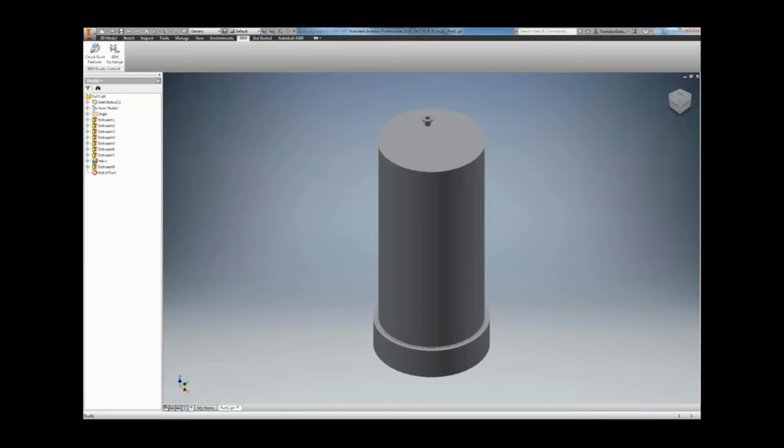So what you can do to collaborate with the Inventor people is get them to give you the ADSK file, which means that there's less work for the plant users to do, and you're going to get a more accurate model of what's going to be positioned out on site. So here I've got this part in Inventor. It's pretty simple. There's a base on this tank, and then just one single nozzle.